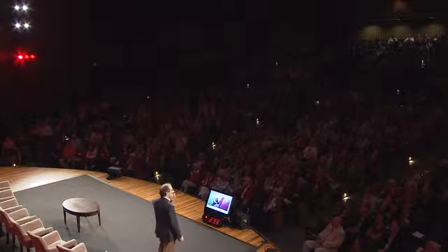What else do you worry about? There's some residual chlorine. It has a very short half-life, maybe 15 minutes in the ocean. More significantly, particularly with the thermal plants, might be corrosion byproducts, chromium from the heat exchanger systems, for instance. It's a bad thing to have in water, and so those types of byproducts need to be considered as well.